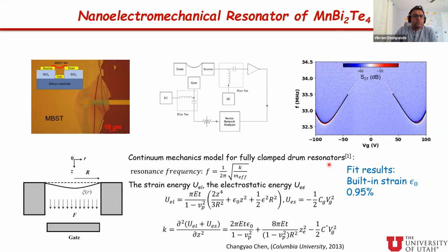Okay, so we use simple continuum mechanics models to model this behavior. This is a continuum mechanics model that shows two different contributions to the overall energy: an elastic contribution and an electrostatic contribution. You then take two derivatives of this with respect to displacement and get the spring constant, which is then used to convert into frequency and can be used to fit this data.